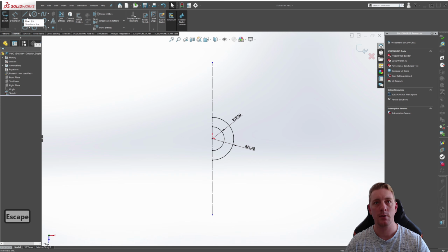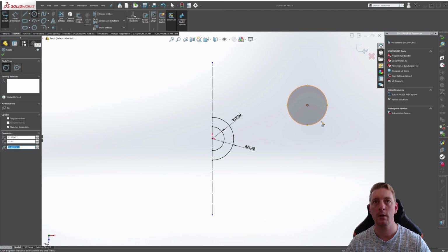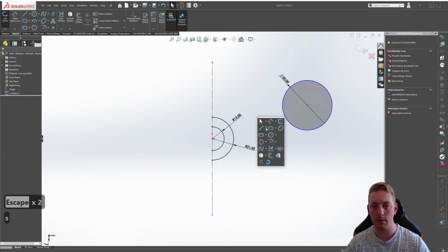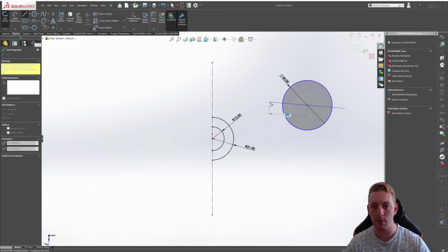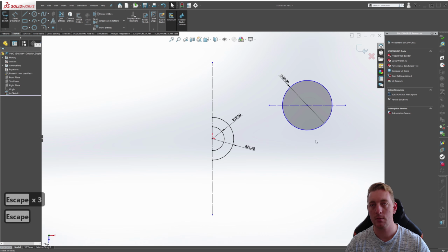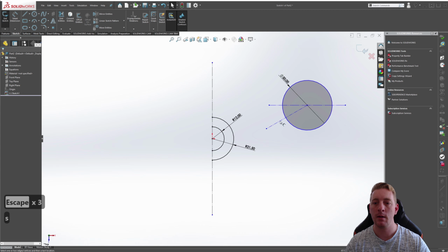The next part is drawing the outside profile. What we might do first, we know there's a circle out here somewhere, and this has a diameter of 50. We might also just put a center line. I'll make that a midpoint line just to make it a bit clearer, and we'll change this to a construction. We also need a center line from this midpoint, which we'll use soon as well, which will be at an angle. And there is a dimension here of 22 degrees. So this is going to come into play later on.